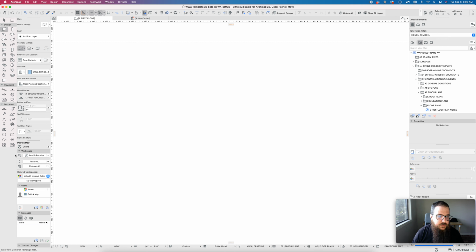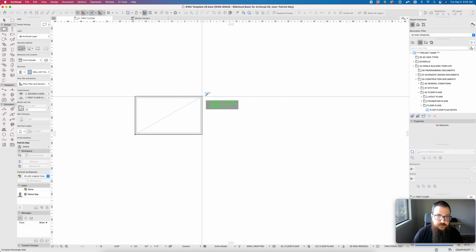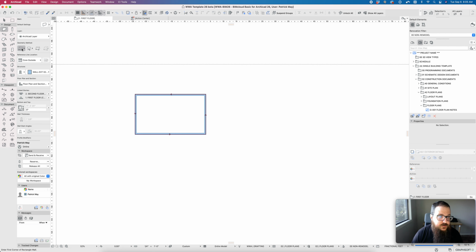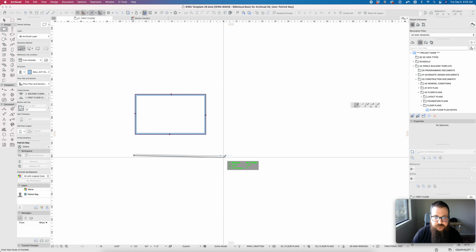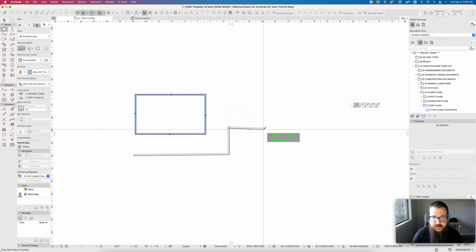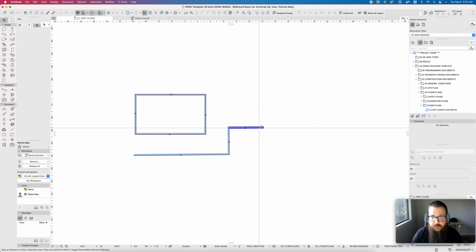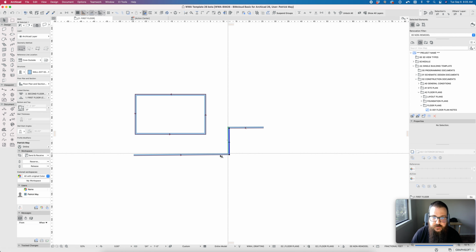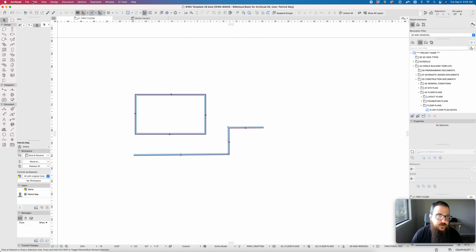Here in the ArchiCAD work environment I'm working from, my info box gives me the abridged shorthand version of the wall tool. Most importantly, with all tools on the info box is this geometry method. This is what allows me to draw out four walls at once, or draw out segments of walls as a running chain of walls. Important to note that these walls are independent of each other. Even if you draw them out together, they're independently selectable.